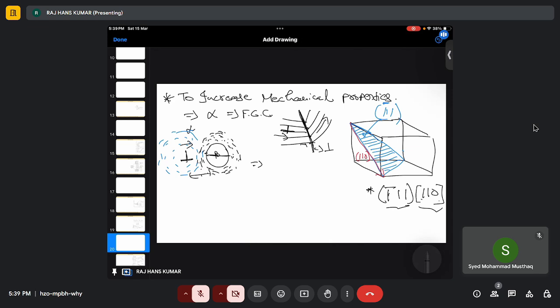The precipitate will look like this, because the top of the precipitate is moved with respect to the bottom one, and that's why it looks like it was cut. This is one way for the dislocation to move past the obstacle.